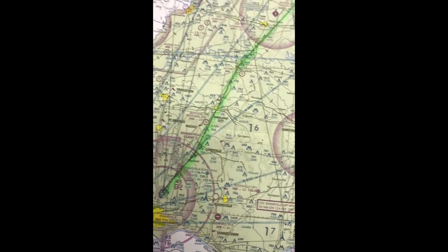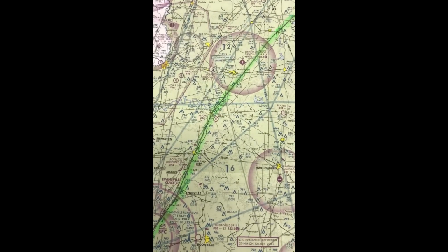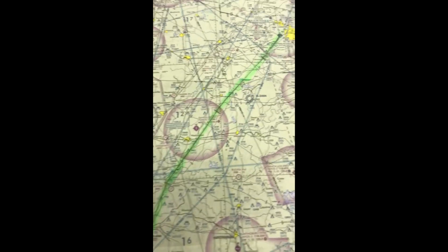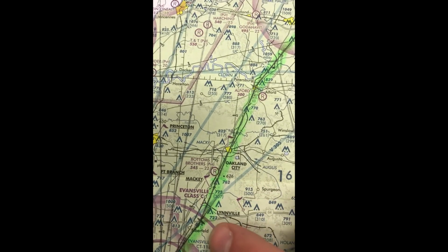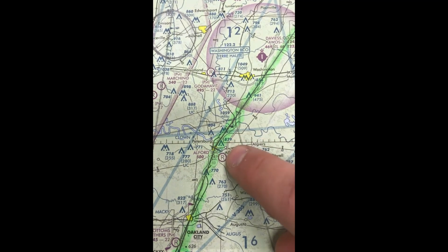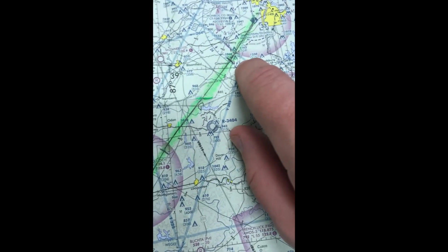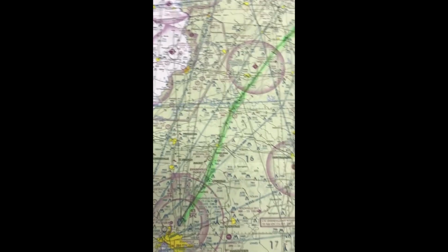For the rest of the route, I went ahead and chose checkpoints approximately every 20 nautical miles. They don't have to be exactly 20 nautical miles, just somewhere in that ballpark. If it's a little more or a little less, that's fine. I connected them all with a plotter, but I was sure to annotate all those navigational checkpoints with some sort of horizontal line so that they're easy to pick out. Then I took a green highlighter and went over the route, so that when we're looking at this in the aircraft, it's easier to see a highlighted route than just a little pencil line drawn on there.